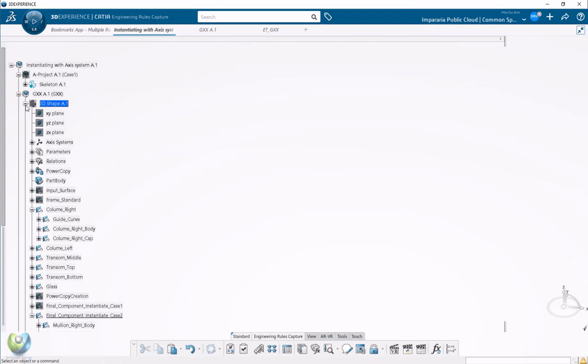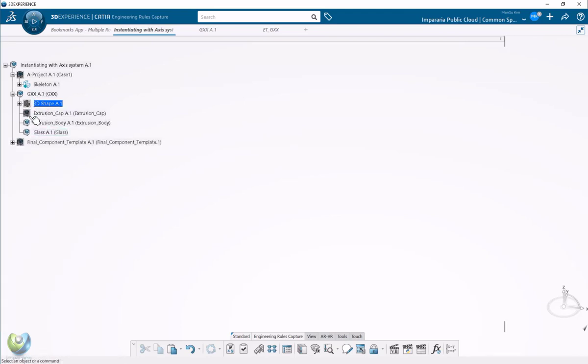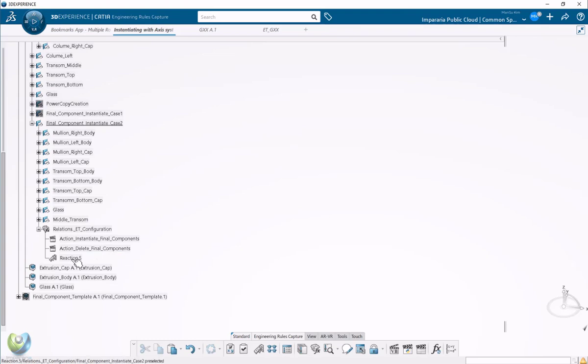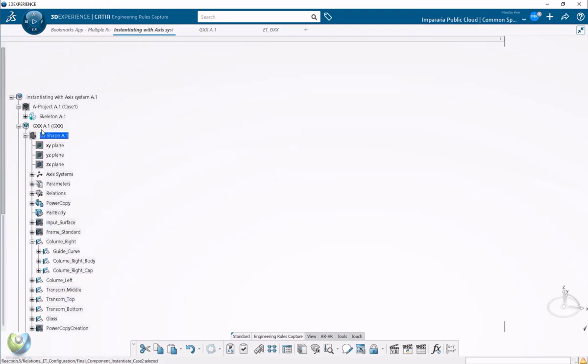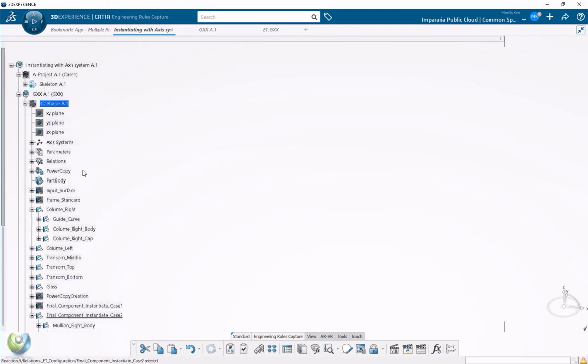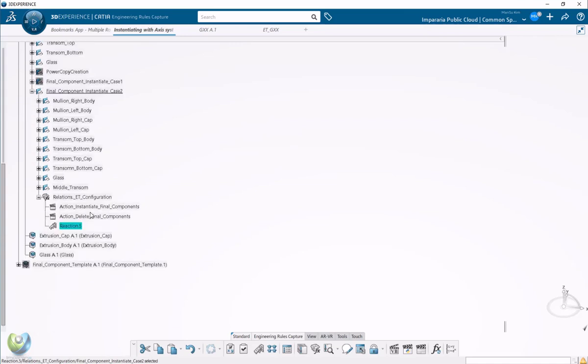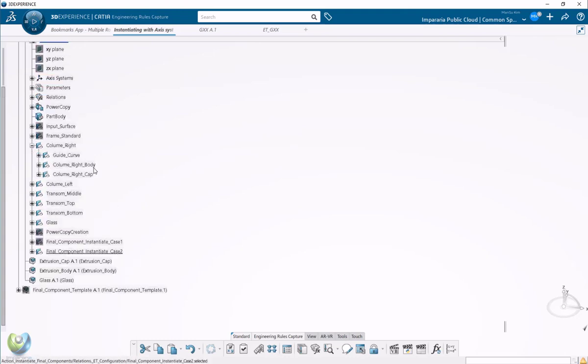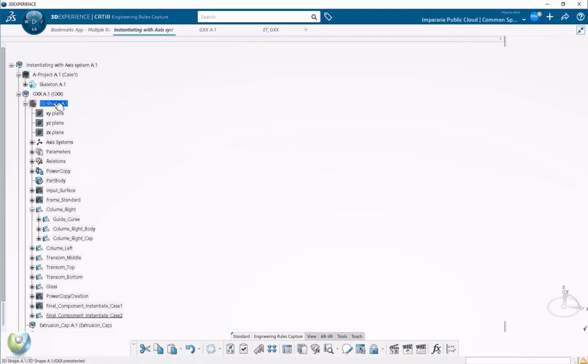So it's better to not instantiate yet, but there's some reaction while you instantiate at the project level. The trigger is when we change the name. When something is changed, then this reaction will allow this automation to run automatically. That is one of the ways without causing errors.